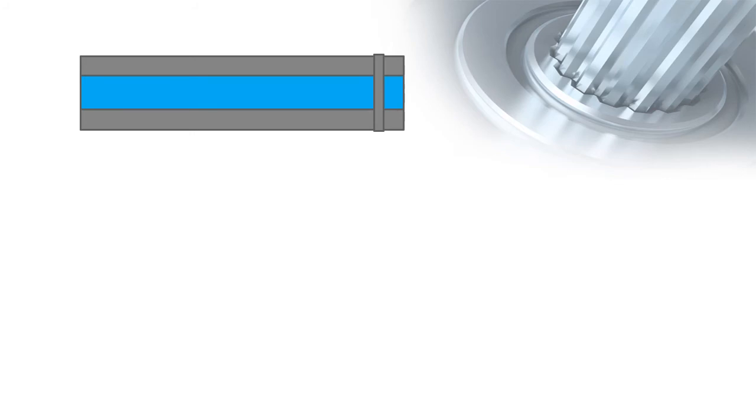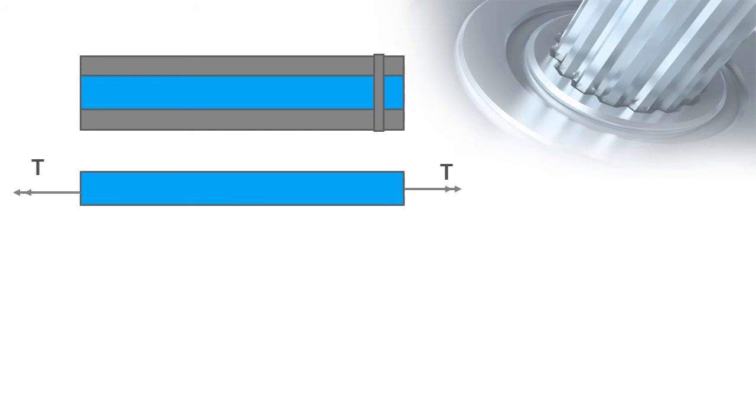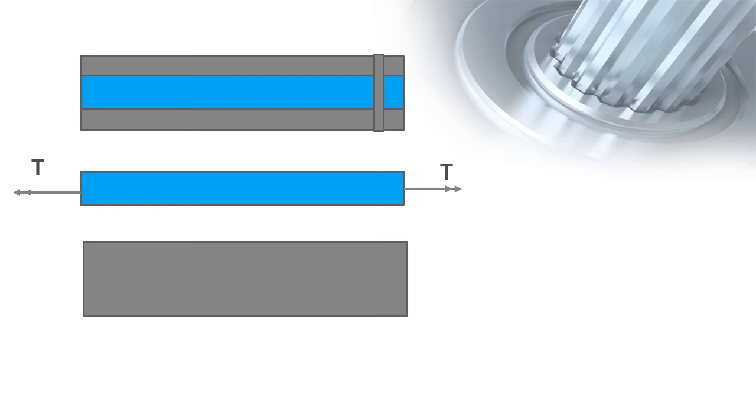Hence, when we dismember the assembly, we should have a torque placed on the steel shaft and another torque placed on the aluminum shaft. Note that the two torques are equal and opposite in direction because the pin only connects two materials, the steel shaft and the aluminum shaft. Hence, by the law of action and reaction, the torque felt by the steel shaft should be equal to the torque felt by the aluminum shaft. Note the directions of the torques.